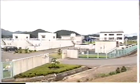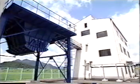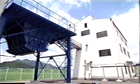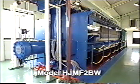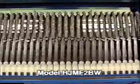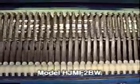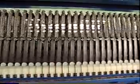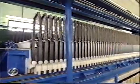At this water purification plant, a KURITA fully automatic filter press is used for the filtration and compression of sludge from wastewater treatment. The filter press operates fully automatically, 24 hours a day. The filter press used here is the model HJMF2BW, which has 86 chambers with 1 meter square plates and a total filter area of about 140 square meters.